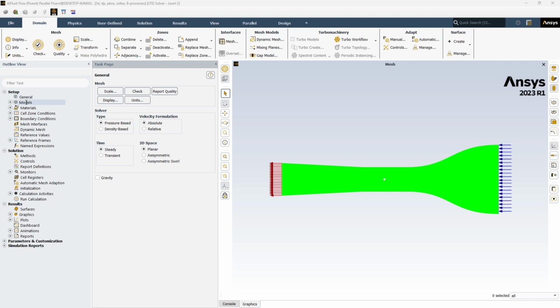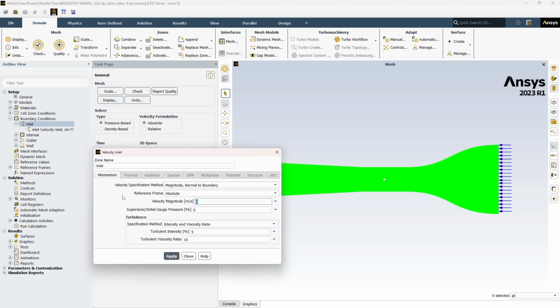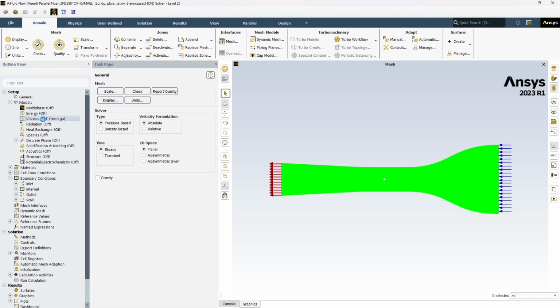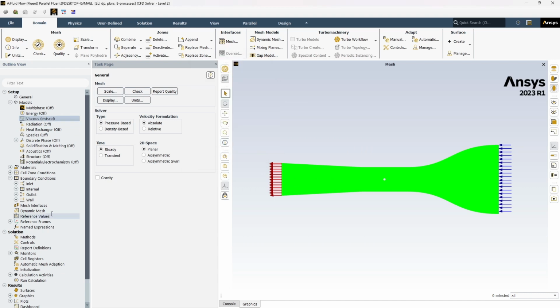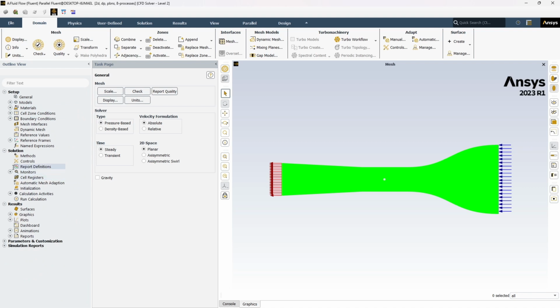All right, here we go. You can see everything's loaded in. Due to the way that we named each section, the outlet and inlet are already set up that way with the arrows. We're going to change the velocity magnitude to what we have previously calculated, going into the wind tunnel. This is going to be the inviscid flow simulation over the cylinder, so change that setting from viscous to inviscid.